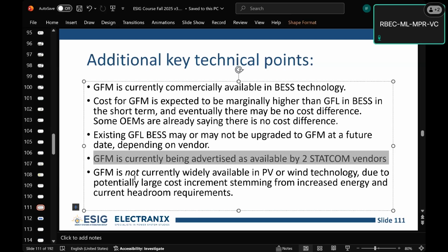Yeah. And when you squeeze energy out of a type 3 wind, you have to give it back, or else you rip the blades off. So you had a graph of it, it kind of looks like FFR, where it would go up, you get a little bit extra power, and then at some point you've got to get energy back to avoid that. Yeah. Although you could also take the same route as the StatComs and say,